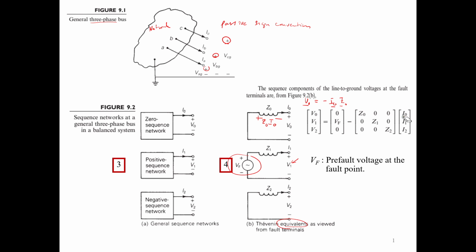So this is how you see the systems. Now we have the polarity in this form. You have the current I1 flowing from left to right, so that creates the voltage drop across Z1 equal to I1 times Z1. So you apply KVL around this loop and get the second equation, which is V1 equal to Vf minus I1 Z1. This is just the normal voltage drop.